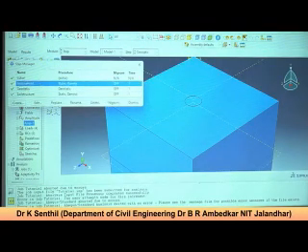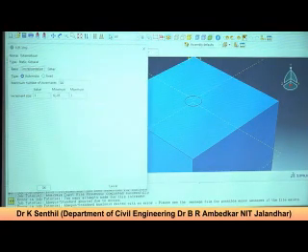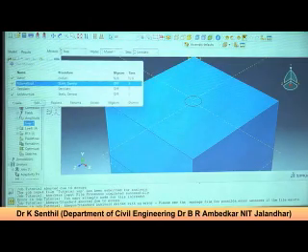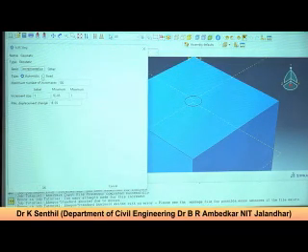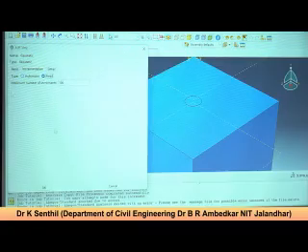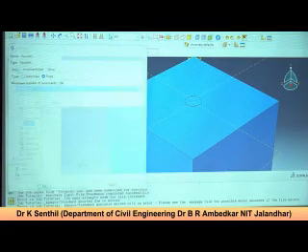So if you see here, whatever we get as initial and maximum time steps. So run it as fixed rather than automatic. Okay. And just try one. I think we'll keep all as fixed increments. And it might converge.